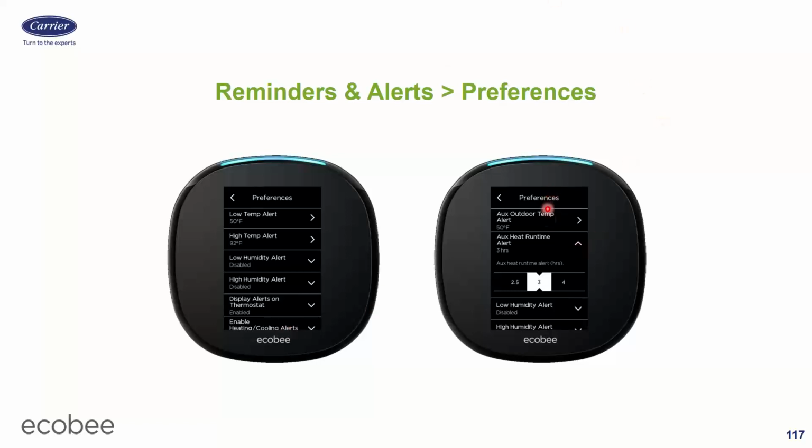If they have auxiliary heat, we can enable some other features on there in addition to the ones I just told you. So only if they have a heat pump with auxiliary heat. So for example, there's this one here, auxiliary heat runtime. In this case, set it for 3 hours. If the auxiliary heat has to run for 3 hours, that probably means the heat pump is not doing its part of the story, right?